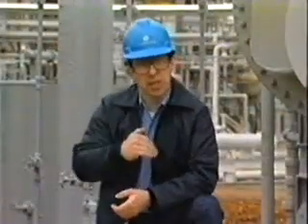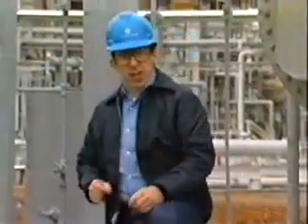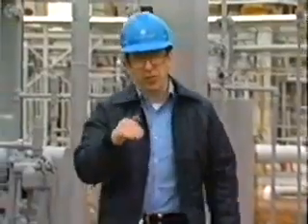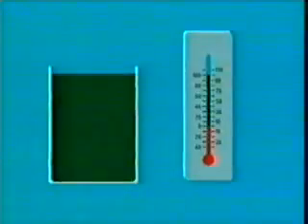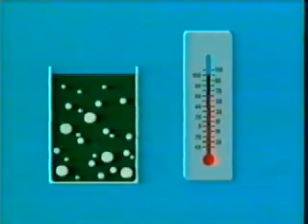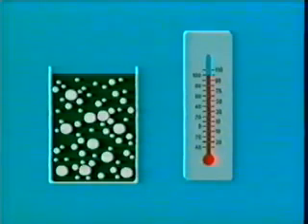The temperature of the incoming gas has a significant effect on the water content of the gas entering the contactor. Remember, at constant pressure, the water content of the inlet gas increases as the gas temperature is increased. The more water vapor that the gas contains, the more water must be removed by the unit to reach the desired water content of the outlet gas.